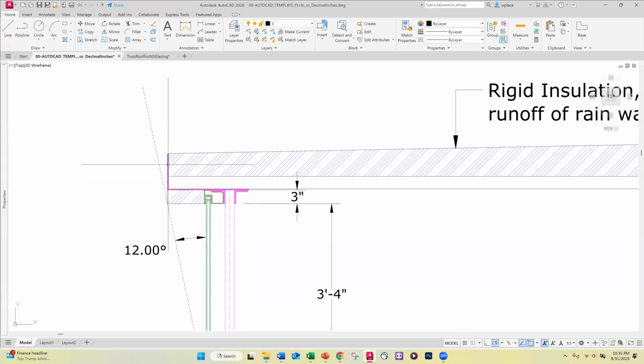So this 8-inch leg of this bent is protecting and sealing off the corrugation. It's protecting the rigid insulation. But there's a problem because outside air is hitting this bent and then conducting through this plate to the inside and also conducting into this 3-inch corrugated decking.